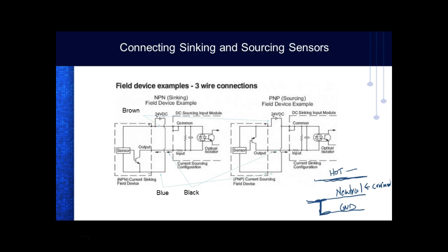So what happens is something happens and this hot gets shorted up against the chassis of your refrigerator or something like that, it'll pop the breaker. Because that way your ground carries a current and your ground is not supposed to carry a current, right? You understand? So that's why they call it that. So you'll see when we get on these AC modules, they'll talk about neutral, hot, and then we always run a ground, right?